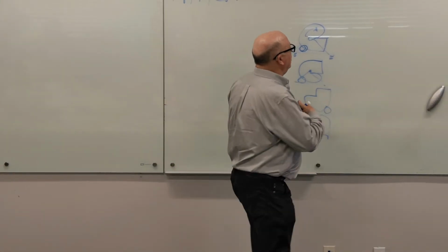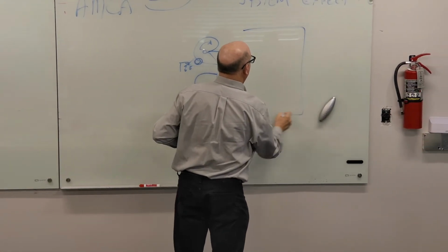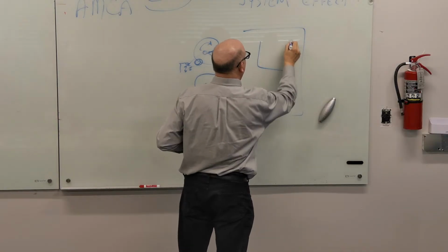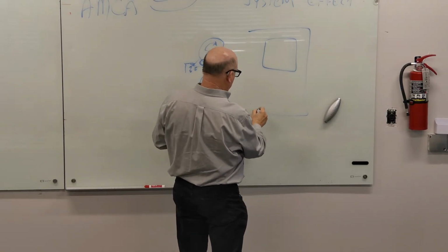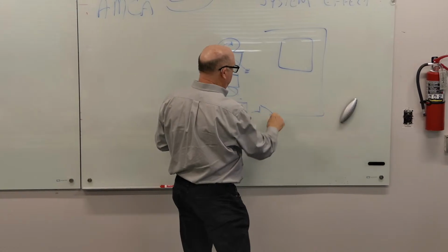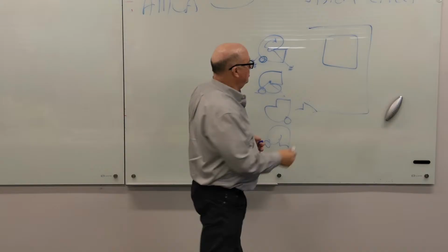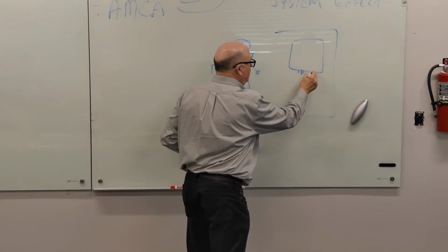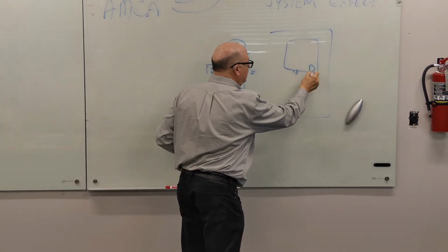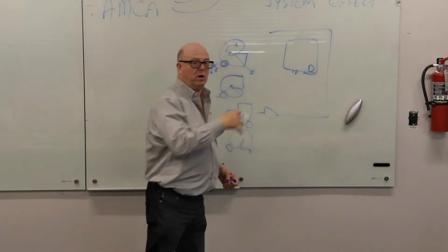Then you look at your equipment room. If this is your equipment room and the air handler is over here in the corner, and here's your door and here's where you walk in, you want to use your pipe connections and you want to have the motor with the electrical connection and the motor access door.